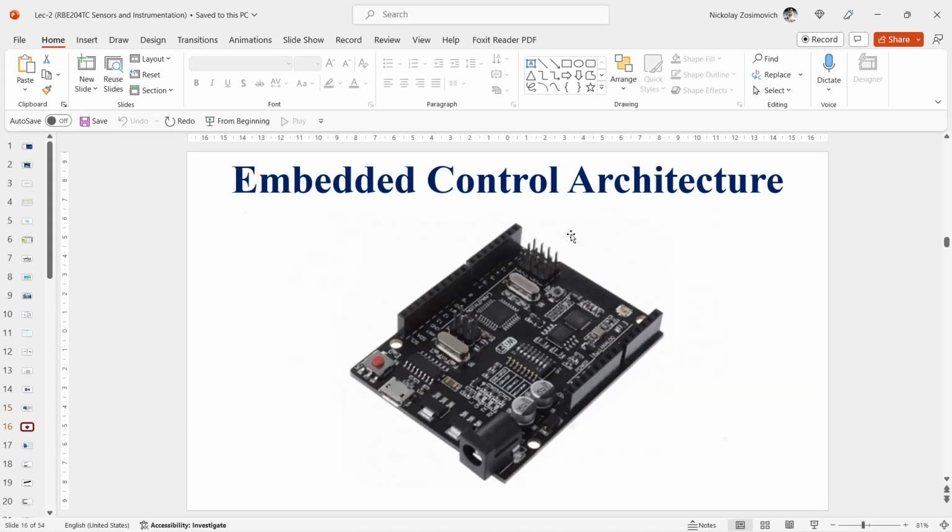The ATmega328P controller, which forms the heart of the discussed Arduino board, is an 8-bit RISC microcontroller running at the same 16 megahertz. The RISC implies that most of the low-level instructions can actually be processed in one clock cycle. This means about 16 million instructions per second. The controller has 2 kilobytes of RAM, 32 kilobytes of flash memory for program storage, and 1 kilobyte of EEPROM.